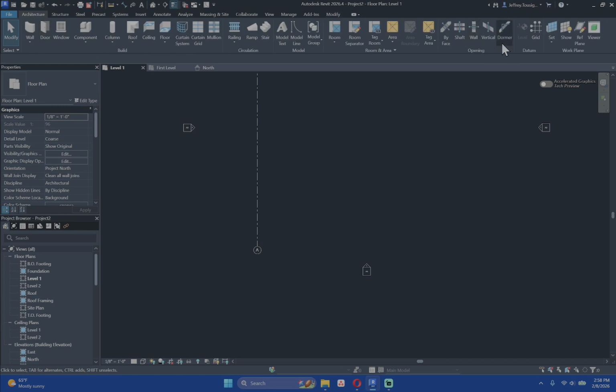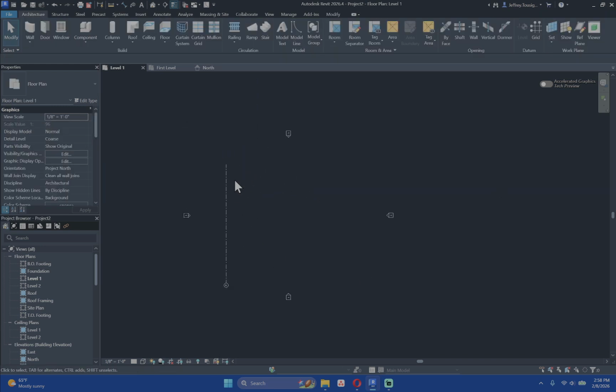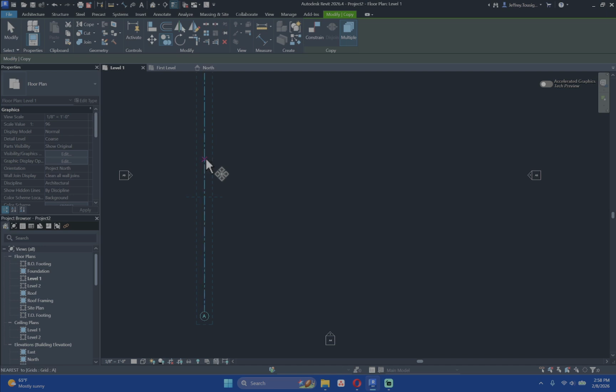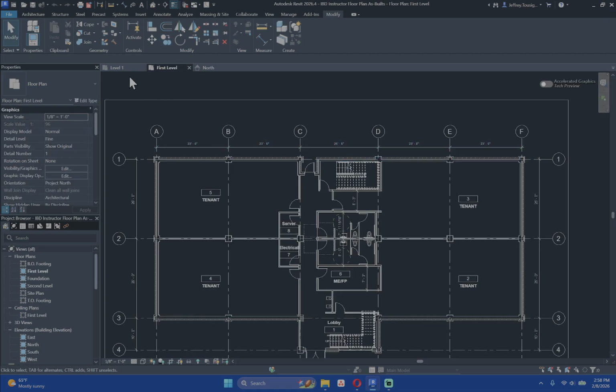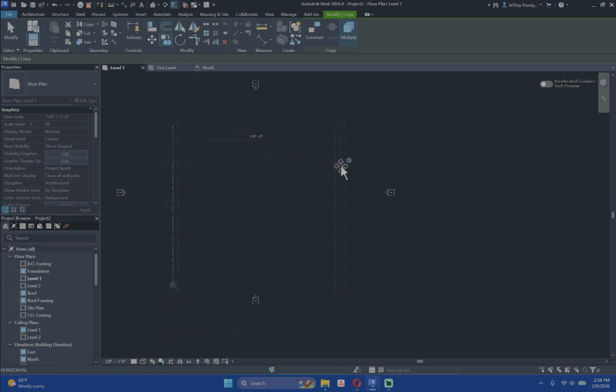And then now when I go to make more grids, actually, I'll just copy it. When I copy or make more grids, it's going to count itself up. I don't know if it's called counting when you're going up lettering. And it is, my bad joke made me forget things, 23 and 25 feet. So I'm going to select that grid and I'm going to copy it over 23 and then 23 and then 25, 23 and 23.